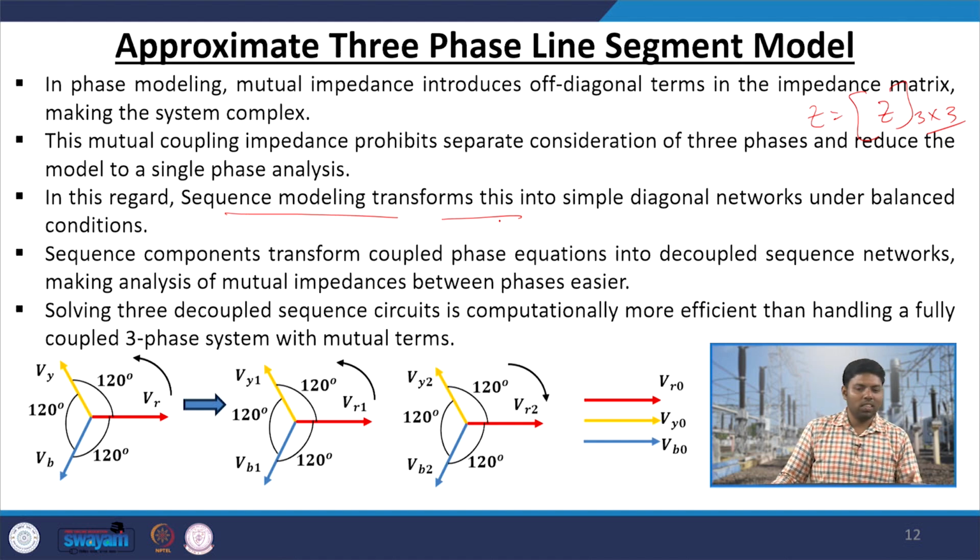If it is a balanced system and you get a fault, that makes the system unbalanced, so there we do the sequence component analysis. Same thing, even at the normal operation of the distribution system, you can use the sequence components to represent your unbalanced distribution network. So, this is your system.